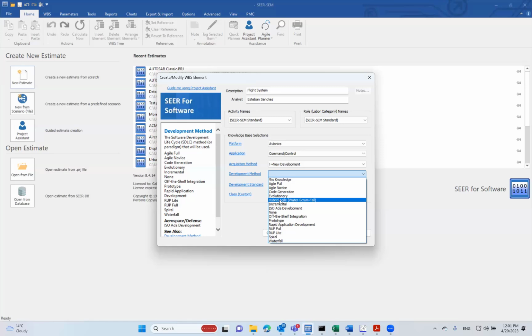However, Do178 requires that you produce a lot of documentation. Do178 asks for specifications, problem reports, review records, configuration management records, quality assurance records, traceability analysis, traceability matrices. So everything has to be very formal. So sometimes organizations end up doing a hybrid between waterfall and agile.